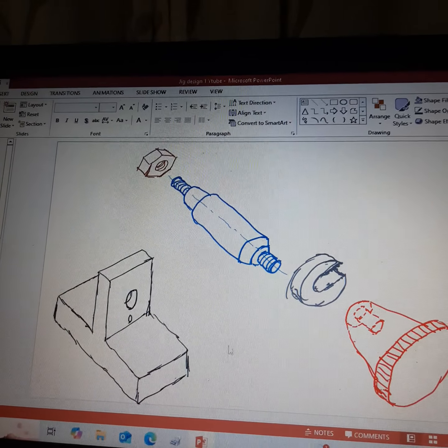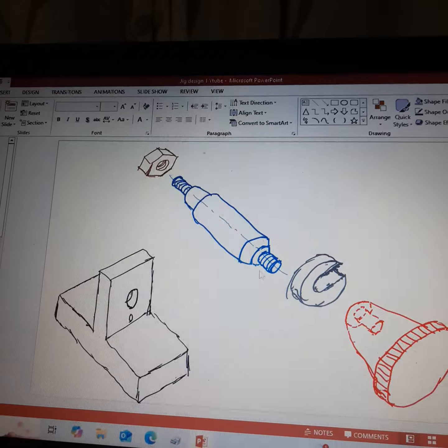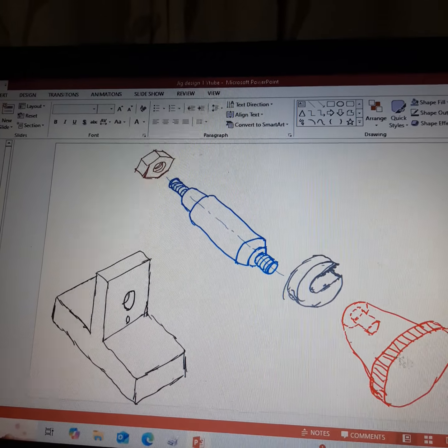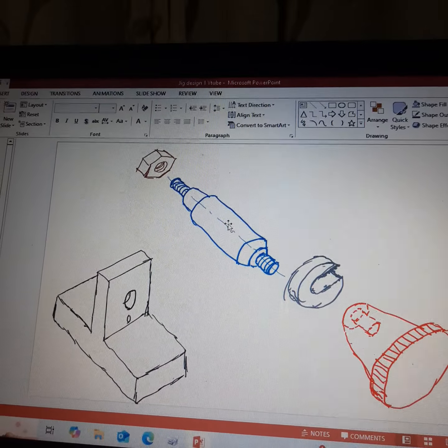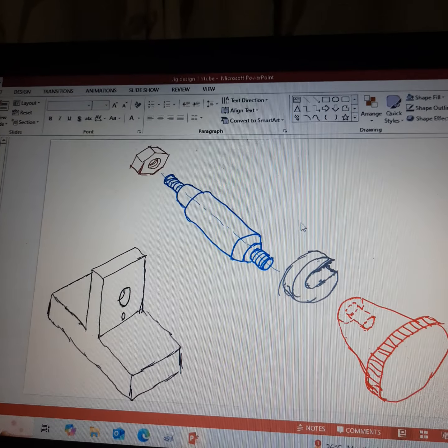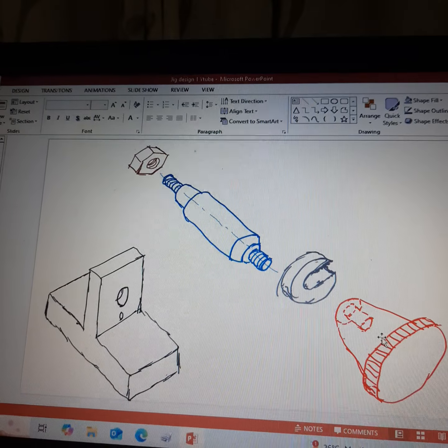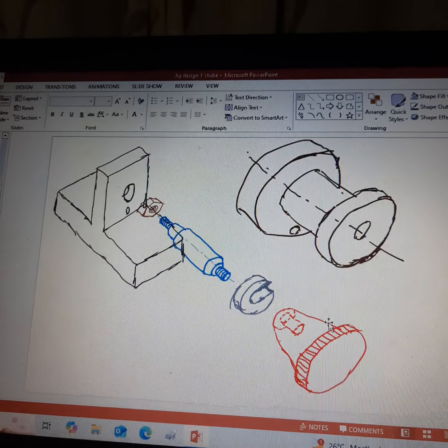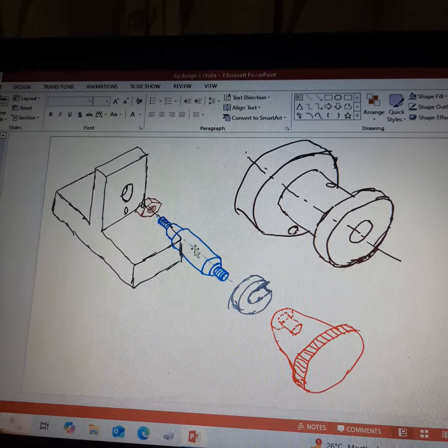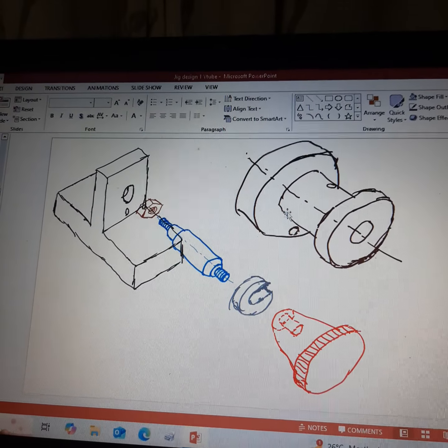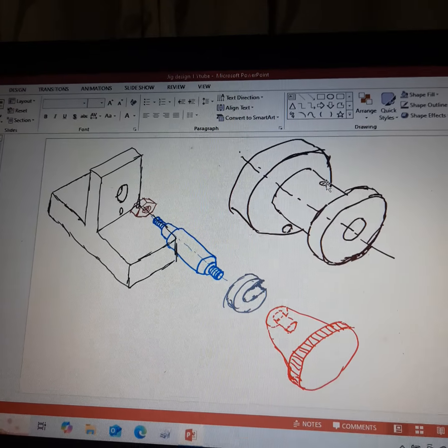We have discussed how to incorporate the locating element and the clamping element. For this example, the location post serves the purpose of locating the component, and the C washer and hand nut serve the purpose of clamping the component. Once this is fitted to the vertical leg, the component can be inserted. Let us say this hole is not present now.